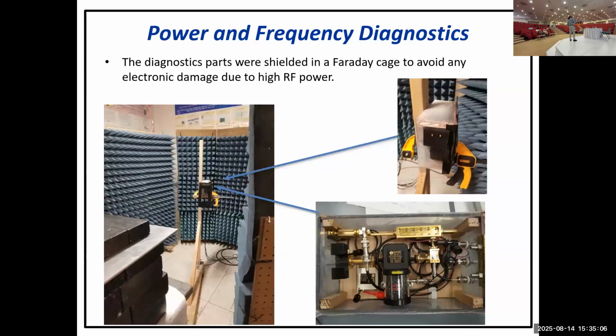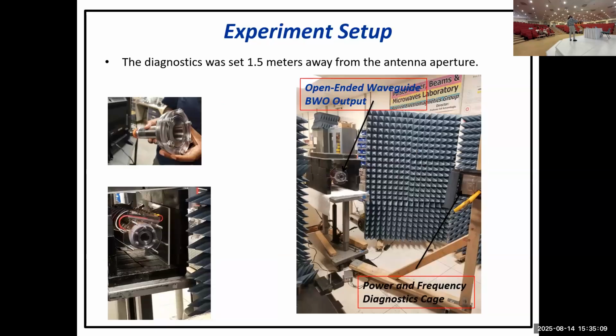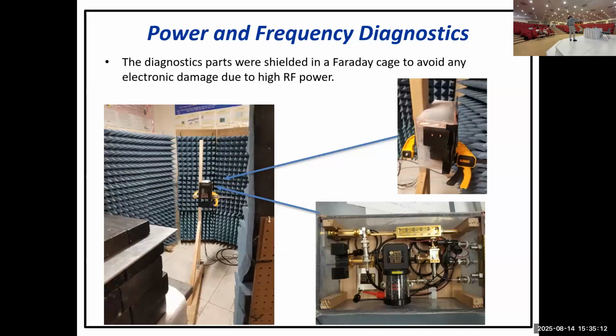So here we have all the receiving equipment shielded because we are radiating high power and very high frequency, 78 gigahertz. We don't have an oscilloscope, and I don't think there is an oscilloscope that can capture that high frequency. So you need to do what you learned in undergrad, heterodyning. Have a mixer and cosine, remember trig functions, take the difference, and do down conversion of the frequency.